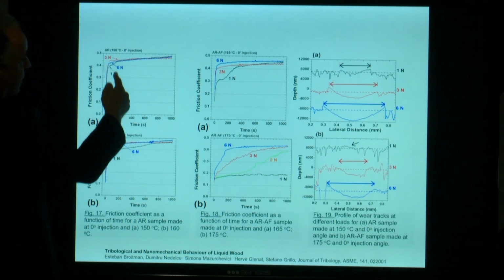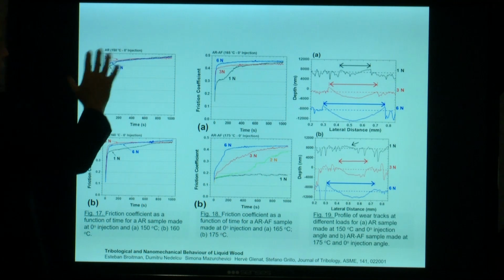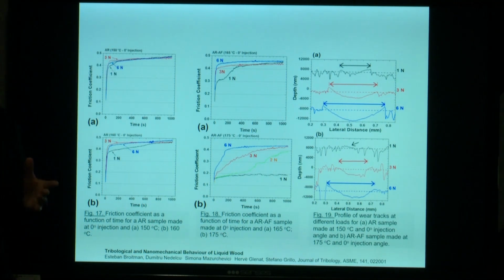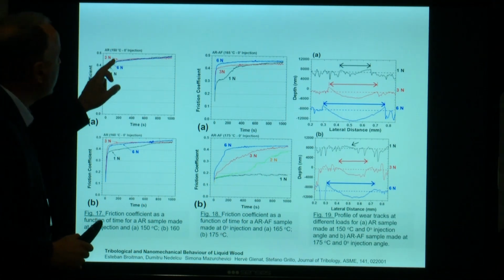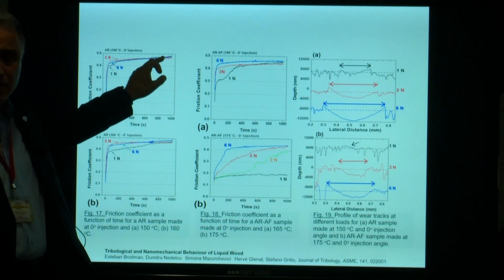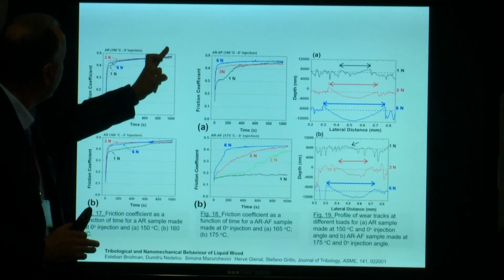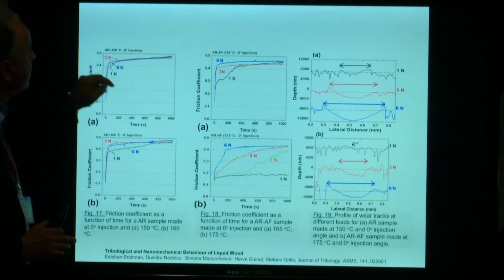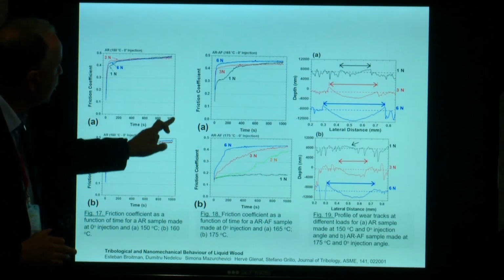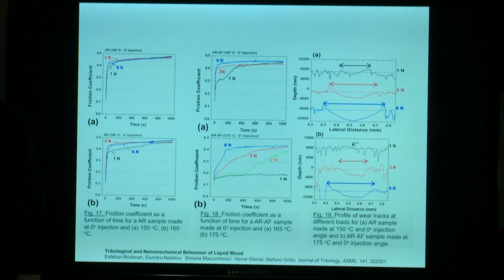Afterwards, up to 200 seconds, the values are the same for all the loading forces, and afterwards it increases, not suddenly, up to, let's say, 0.44 during the 1000 seconds. This is also a good result from the friction coefficient point of view.